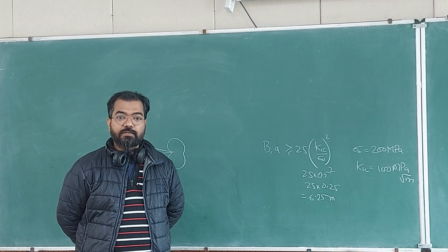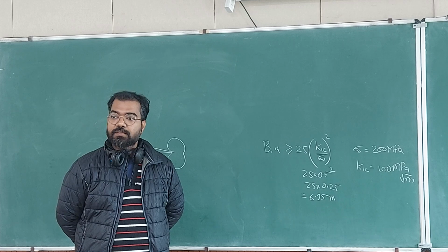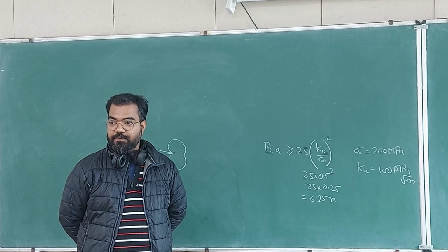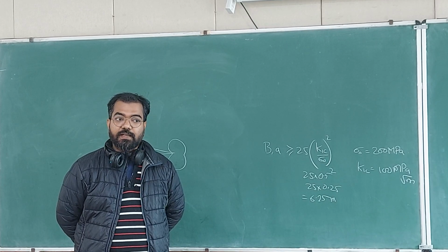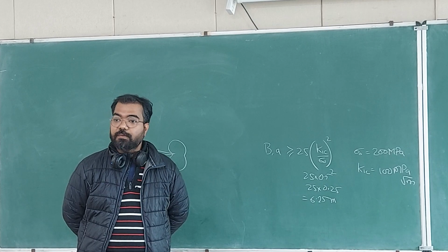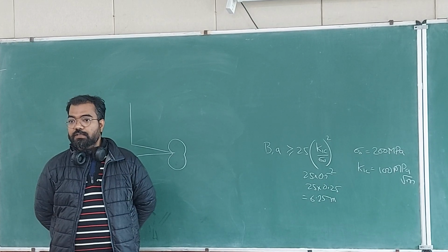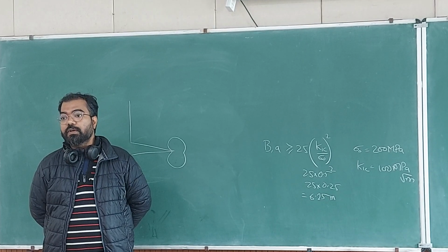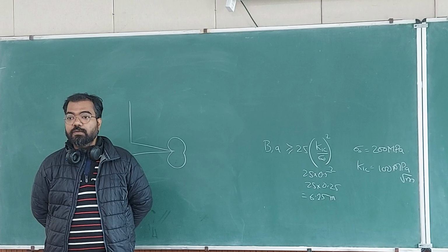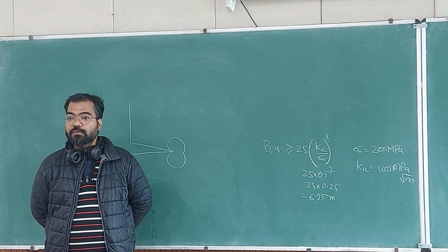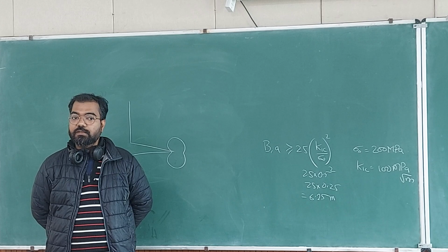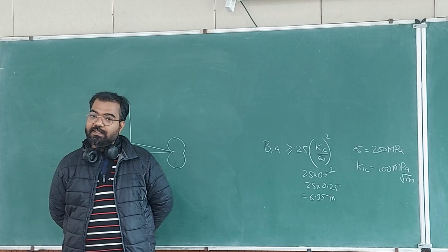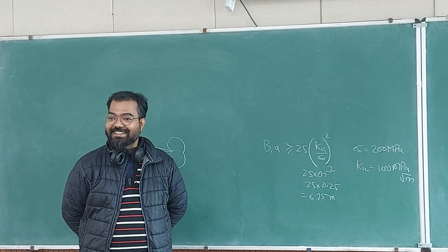18 feet. So the tallest person, 6 feet. Imagine 3 times that, and you have to make a specimen that thick. And the W will be double that, right? So 36 feet, and then the height will be 1.2 of W. So how much? 41, 42 feet. You made a sample somehow, taller than a building, now where will you get a UTM for it?